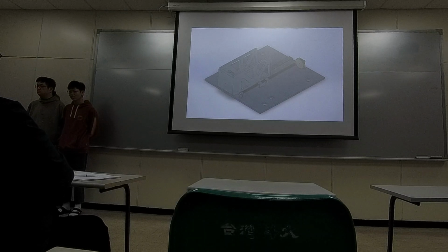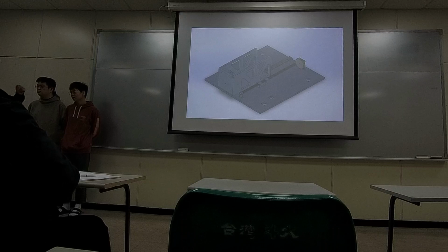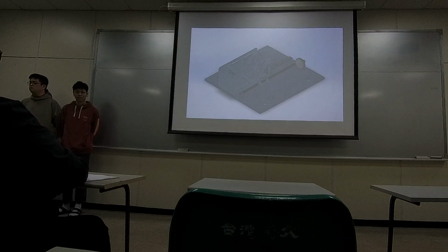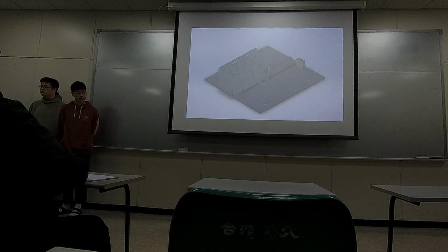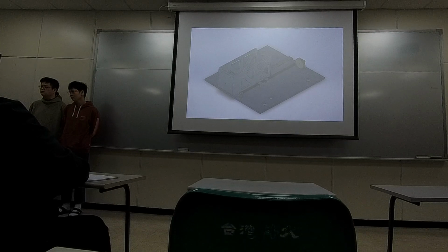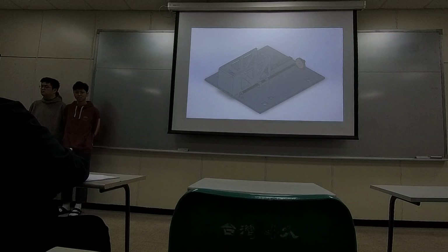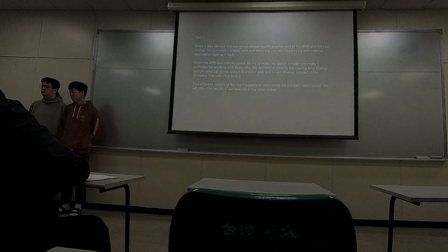So we redesigned the entire horizontal axis, which is on this base plate. As you can see, here we have the dovetail horizontal axis on which the moving part moves. And also we have a worm gear to ensure the moving of the moving part.